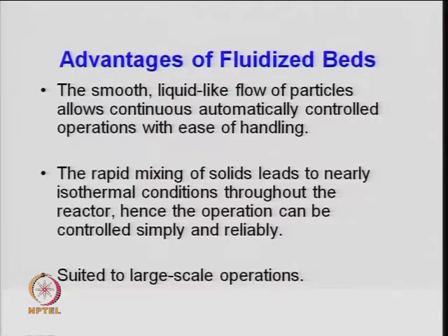So, RTD is generally calculated from e to the power minus t divided by t bar, right, and integrated over the whole range from 0 to infinity, dt. So, the concentration profile needs to be checked based on the radioactive tracer, and then one needs to utilize that for the mean conversion which I was talking about, right, for the given system. So, that is again an issue here, that your residence time t bar is not definite, there is a variation in that residence time, right. It may vary depending upon the flow condition.